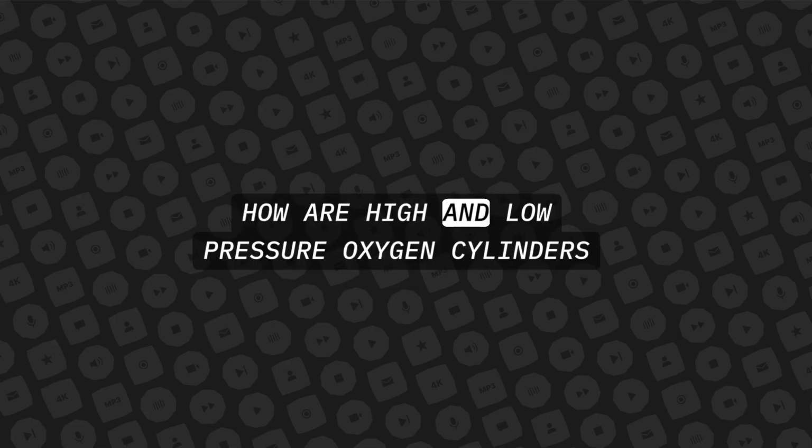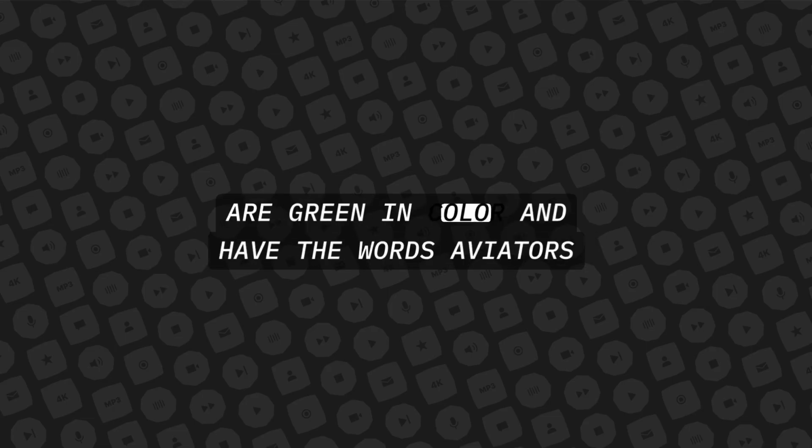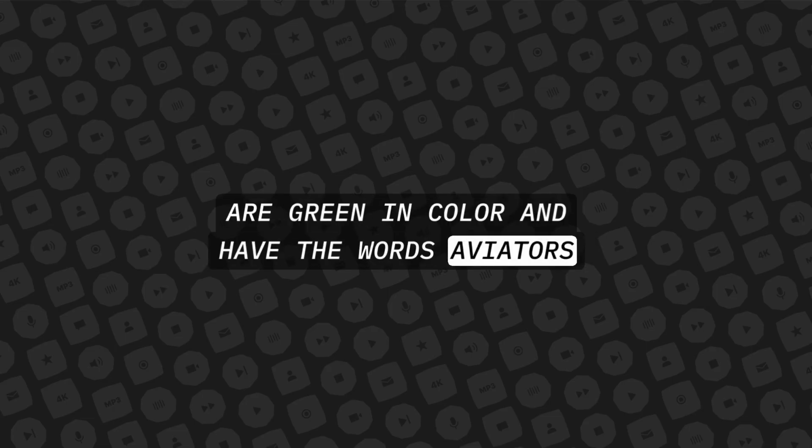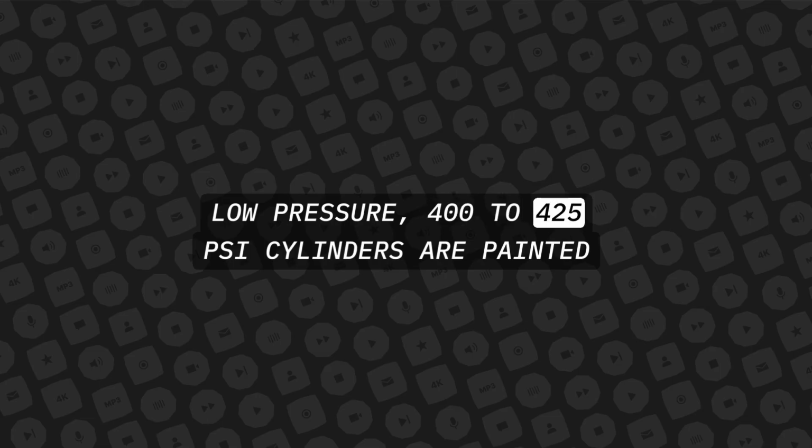How are high and low pressure oxygen cylinders identified? High pressure, 1,800 to 1,850 psi, oxygen cylinders are green in color and have the words Aviators Breathing Oxygen stenciled lengthwise in white, 1-inch letters. Low pressure, 400 to 425 psi cylinders are painted light yellow.